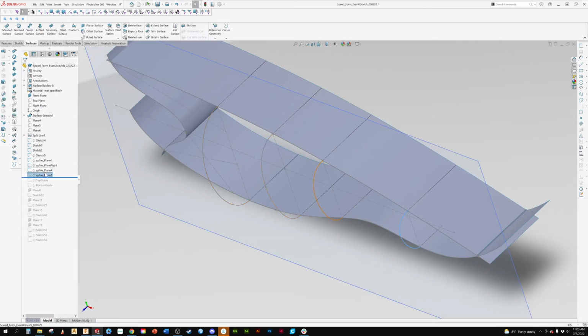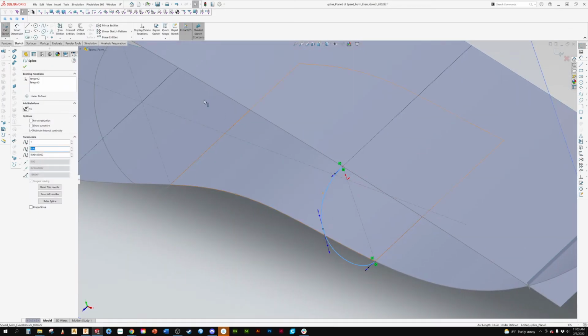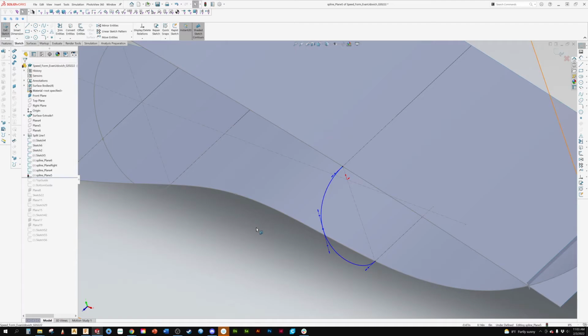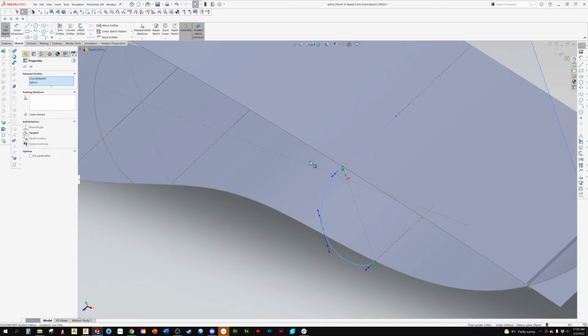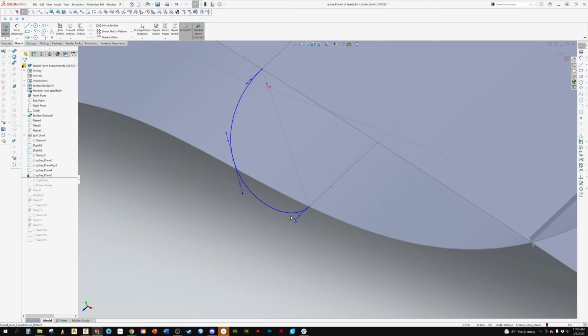We'll come in and do this one. We are going to remove our tangencies right now because they are snapped to those lines, as I mentioned, versus snapping to the surface edge, or the split line in this sense, which actually means that we've broken this out into multiple surfaces. So really, saying that attaching it to the surface edge is inaccurate.